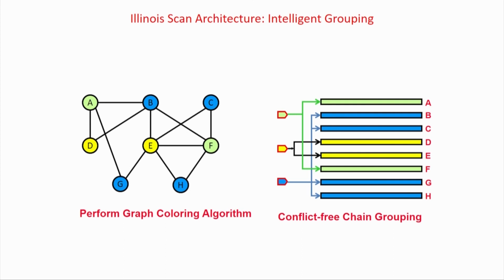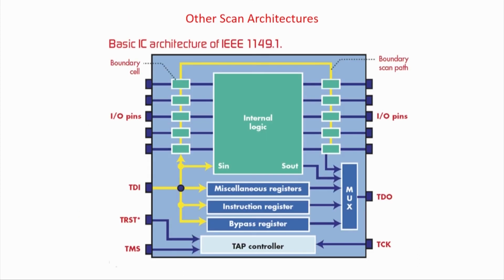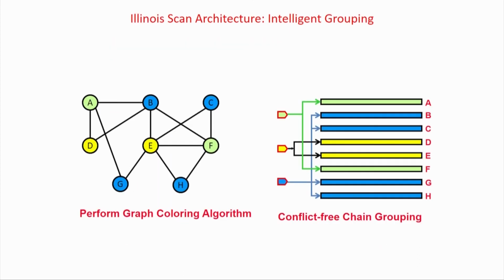So the problem is very simple to design, very simple to map, but solving will take a long time because in such cases of big circuits the graph itself will be large. So we will follow different types of heuristics to solve the problem. So now, this is about basically your flip-flops, scan chains, partial scan, and of course with Illinois scan architecture you can also embed partial scan business to make the problem more interesting and more practical.